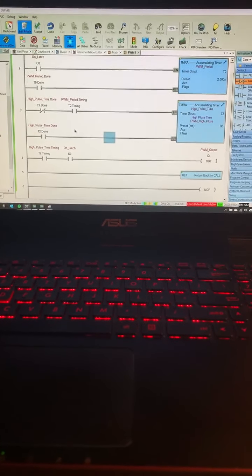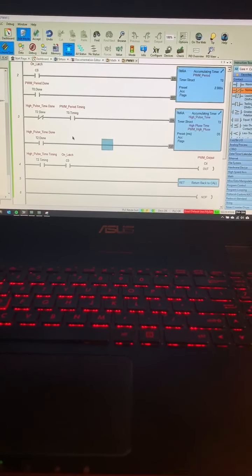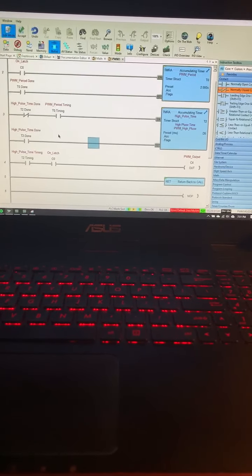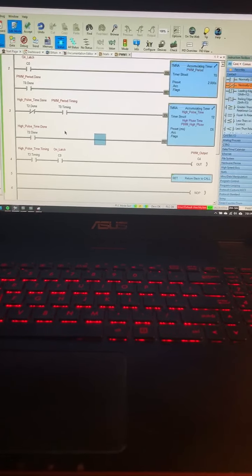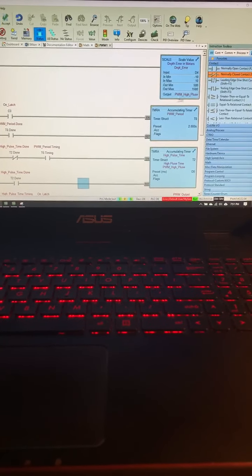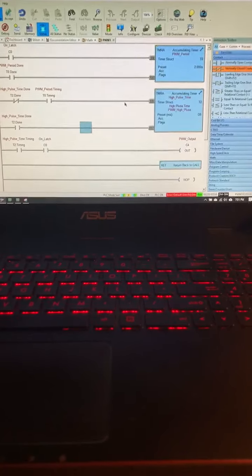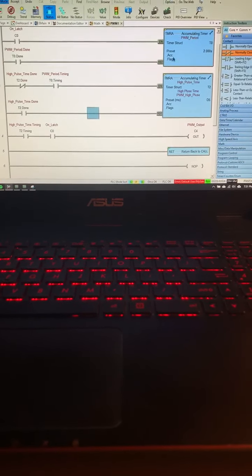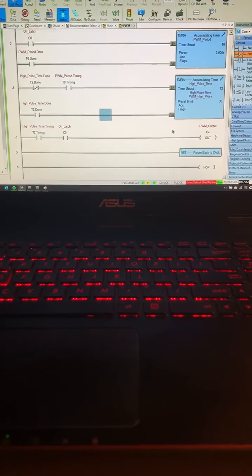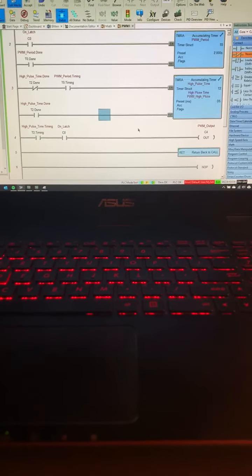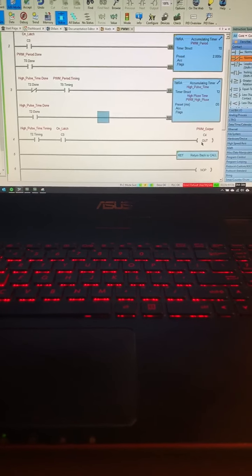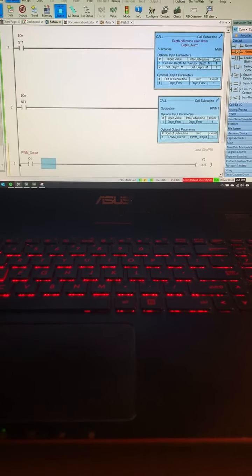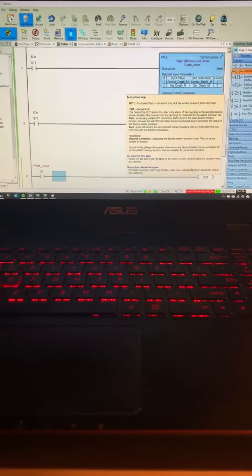And what it was supposed to do was, when the period timer resets, it will time for whatever the value of the output up here, whatever this pulse width high pulse output is. It'll time for that and then cut off until this timer resets. When this is timing, C4 is high. So that would be our pulse width here on the main, so we'd have C4 be high, turning this on high.